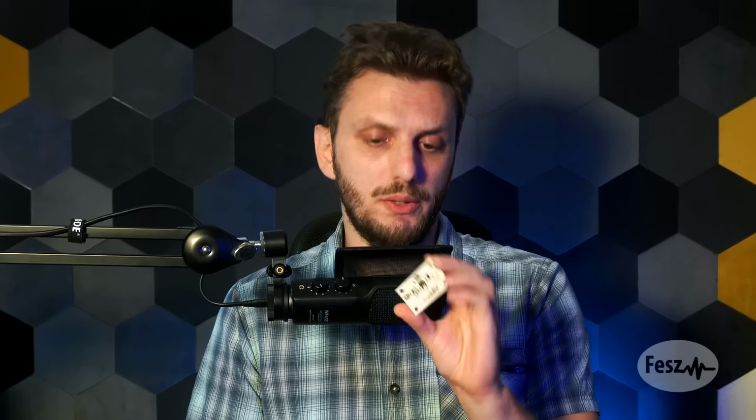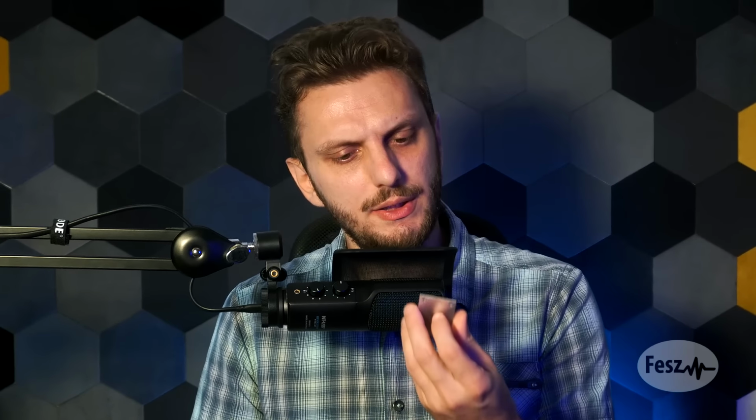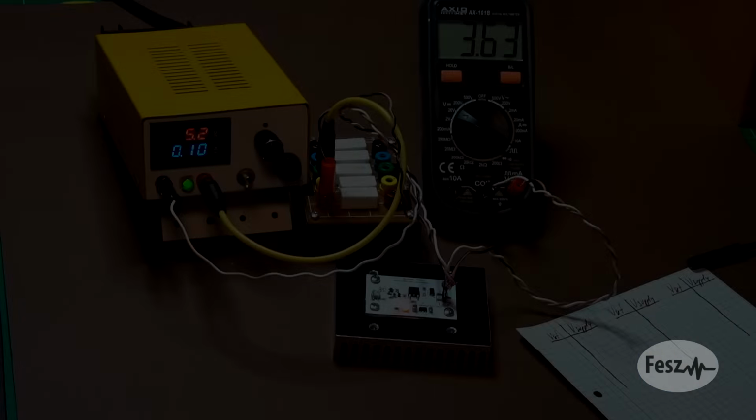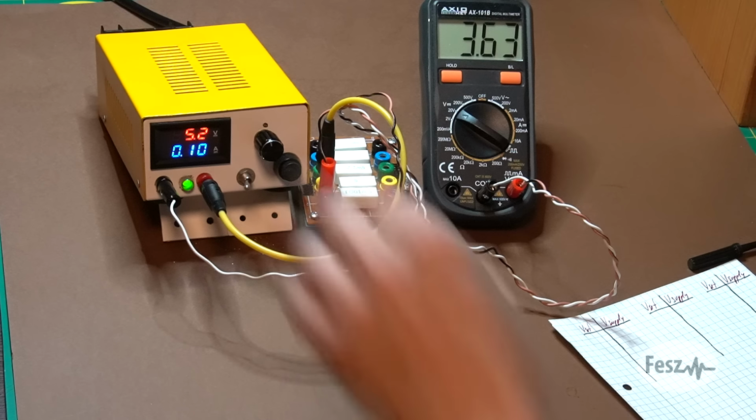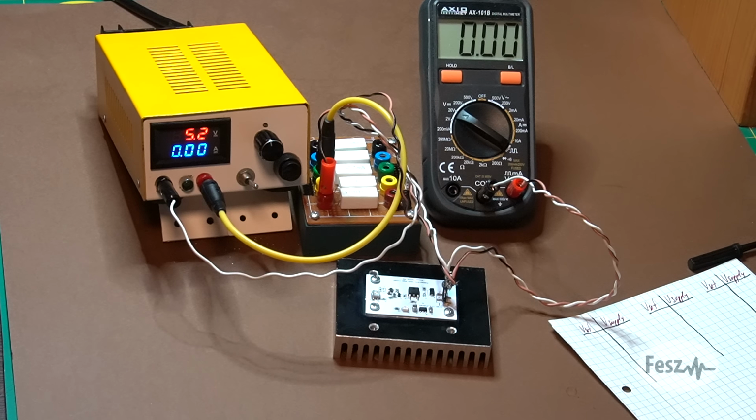Now, the nice thing about such a substrate is that if you have small power dissipations, you can just use it as is, or for larger power levels, you just assemble this to a heatsink. However, regardless of the assembly method, there is no separation in the electronic circuit. It's just one piece, so it's far easier to assemble, and it's more robust than if the components would have been separated. Now, after a short set of tests, I can confirm that all of the circuits do operate.